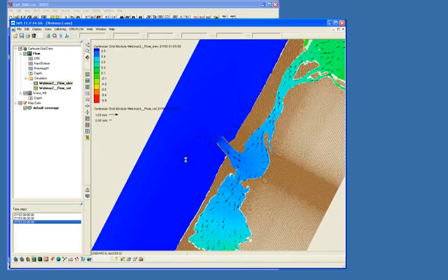Basically what that does is it raises the vector field 2 meters above the elevations of your solution. What was happening was the tides were above the mean sea level, but the vectors were represented at that 0 level, so they're kind of covering up these vectors a little bit. By lifting those vectors, you can actually see everything that you need to.